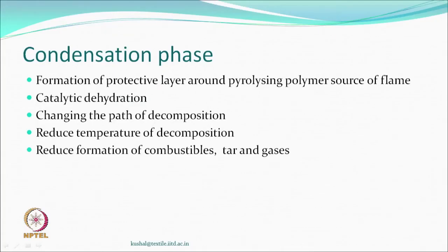They may help in reducing the temperature of decomposition, because only at certain temperatures certain types of products are found which may be fire hazards. And so, if you reduce the temperature of degradation and decomposition, you may be able to restrict or retard the process of burning and degradation. Also, during this process of alteration, they may reduce the formation of tar and gases.